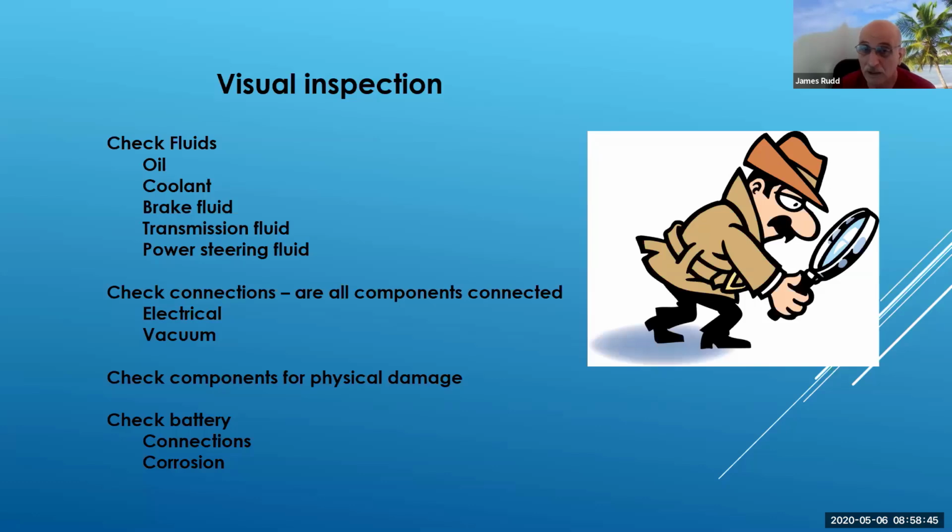But you keep that in mind when you go around the block, and you start feeling the transmission slip. The other question you need to ask is, when was the last time the transmission fluid was actually serviced? And then steering fluid, if it is not electrical steering, but a hydraulic system that actually has steering fluid. I want to look at it, to make sure that vehicle stays in good condition, even after I've driven it. This is something that doesn't get serviced very often. Just like differential fluid in your rear-wheel drive vehicles, there is a service interval on all fluids out there.